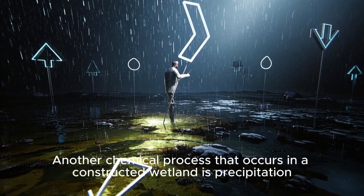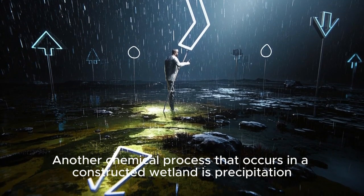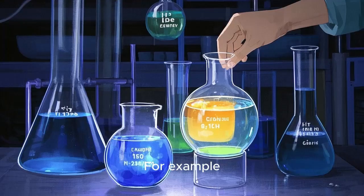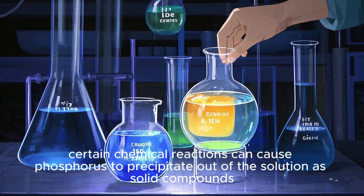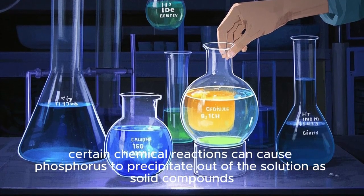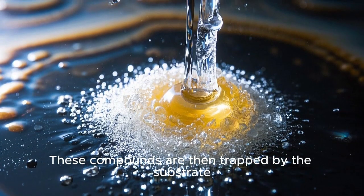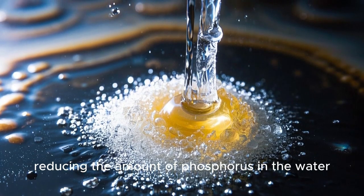Another chemical process that occurs in a constructed wetland is precipitation. This process involves the formation of insoluble compounds that cause pollutants to fall out of solution and settle to the bottom of the wetland. For example, when treated water passes through the wetland, certain chemical reactions can cause phosphorus to precipitate out of the solution as solid compounds. These compounds are then trapped by the substrate, reducing the amount of phosphorus in the water.